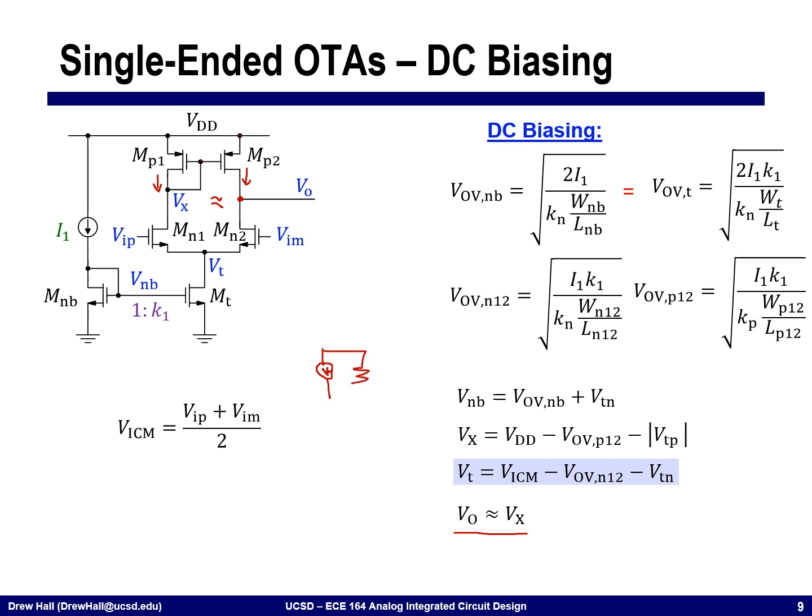So we have a gm and we have an r0. If I have, let me explain it this way. It's essentially like I have two current sources and they're connected together, and we ask what this internal node voltage is. So in an ideal sense, if these are perfect current sources with no output impedance, this can be any voltage.